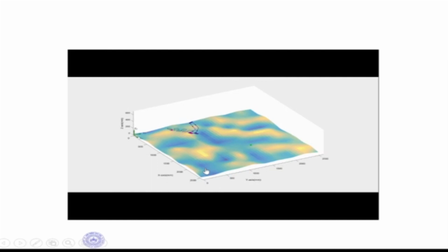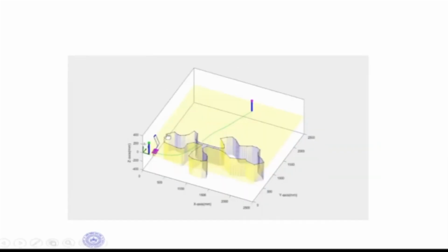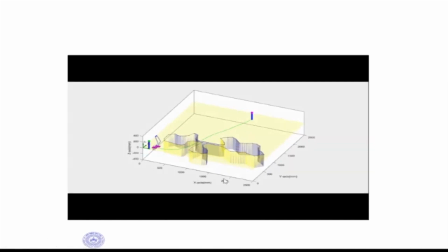It is exactly the same as the wavefront planner that we studied. So the waves try to keep to flat ground. They don't try to climb gradients. So this is a case of a biped robot walking on 3D terrain. Now you can have a biped robot. Suppose this is a ditch. So this place is a ditch. It should not go inside the ditch. So the ditch manifests itself by a very high gradient. So the robot avoids that high gradient and tries to find a location where it can cross, by using the wavefront planner, and then crosses at that point and goes on the other side.